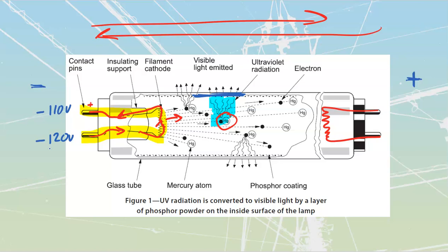Okay, inside of here as well, we do also have the tubes evacuated. If you've ever popped one of these by accident, they make a sort of sound when they pop, and it's not because they're under pressure, but rather because they have been depressurized, and then we place in a small amount of other gas. We call it an inert gas that we would have inside of there. That gas is going to be a mixture of our neon types of gas. Neons are types of gas that will easily ionize and allow us to conduct electricity through the air. So we take out the regular mixture of oxygen and carbon dioxide and all those other things, and we replace it with argon, sometimes a little bit of neon that's going to be inside of there, sometimes we get a little bit of krypton.